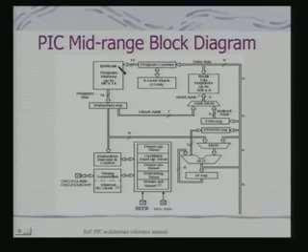the instruction. The interesting feature is it has got a hardware stack. Why is the hardware stack there? Because when there is a call or there is an interrupt, the program counter value has to be saved to enable return to that same location. We know what the stack is used for in calls and interrupts for general purpose microprocessors.